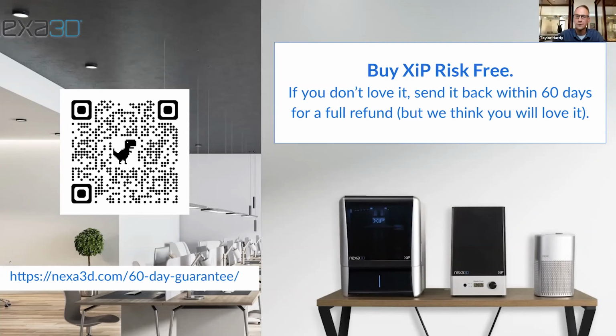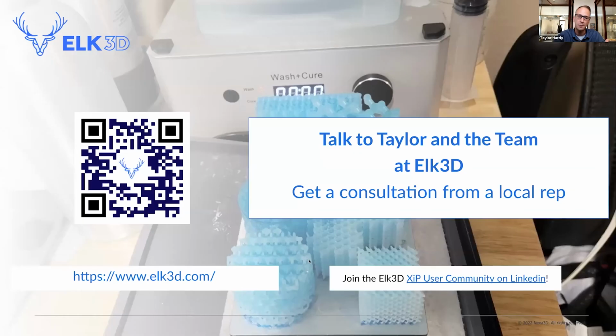Well, and just so everybody knows, on the other end, things that you buy open source that are incredibly high viscosity, you have to be aware that you're using the correct profile. So that's going to require a little bit of testing. Obviously you want to pick the right orientation, but you also have to make sure you have the right supports, and you're not going to get any kind of warping issue when you go to print. So it's really somewhat easy. You just have to use a little bit of caution.